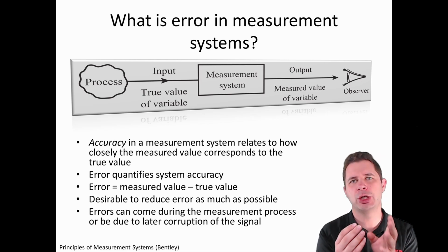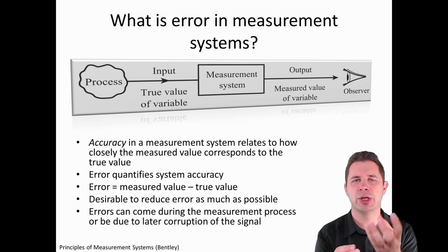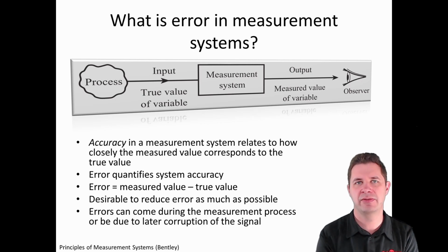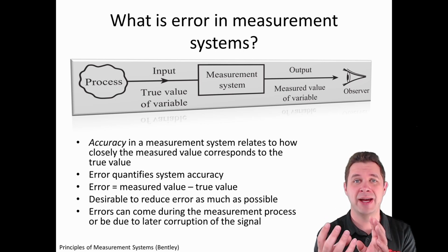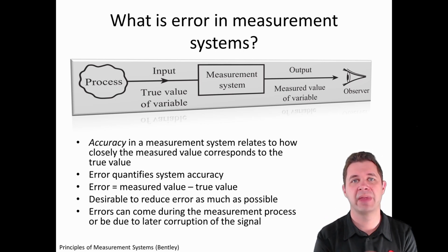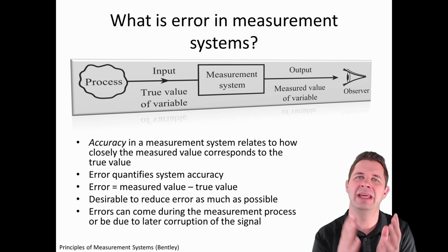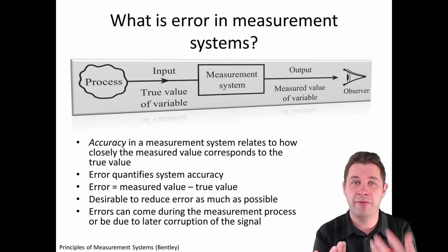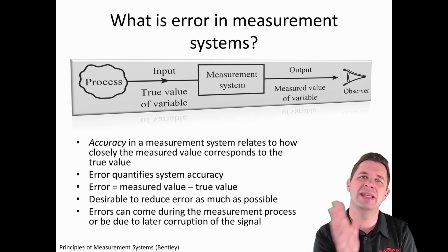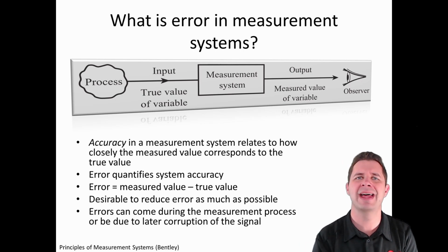For example, if we've measured temperature and we've got a temperature measurement of 24.3 degrees, what's our actual temperature? Maybe it's 24 degrees. And that difference between the actual and the measured is our error. So our error, we say, is measured value minus actual value. Or if we think about our measurement as a complete system, it's the output of the system minus the input of the system, in terms of the output as a certain measurement in temperature or volts or g-forces or whatever it is, minus the input of the system in terms of whatever unit that is.